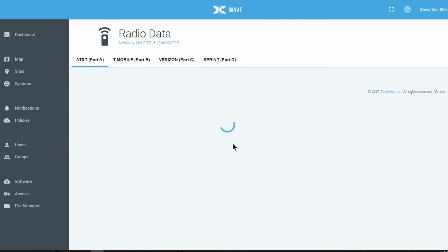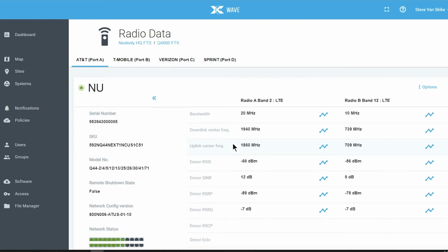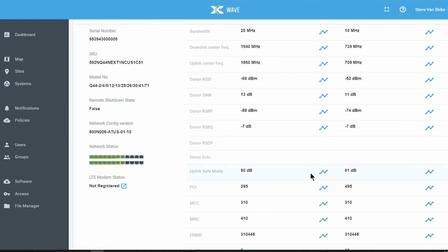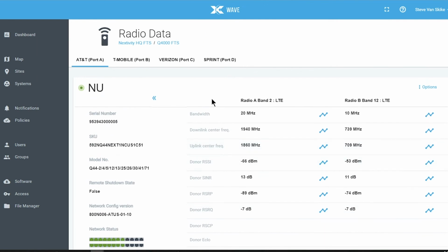If you have multiple systems in the same building, which is very, very common, and they're actually feeding back in through each other, System A cannot echo cancel a signal that's coming in from System B. It'll lower its gain to get rid of an echo, but the echo isn't going away because it's coming from a different system. So it continues to compensate until its downlink gain is 0. Same thing, I go back out to the coverage units and turn them off one by one, and I'll try to find out which coverage unit is feeding back into some other system and then go create better isolation for that system. So that's pretty much everything I do when I'm evaluating something.